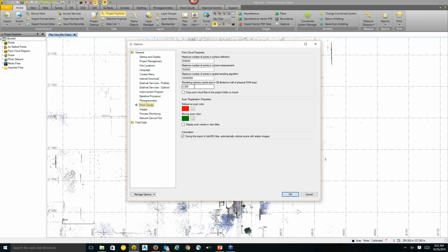Which leads to one of the questions: what are the physical requirements or computer hardware requirements for working with point clouds? We strongly recommend that you have an external graphics card, even a basic NVIDIA, I think an M1000 or something like that would do the trick. I think I have here a basic NVIDIA with a 2 GB graphic card. You don't have to have a super computing or gamer's graphics card. It will work okay.